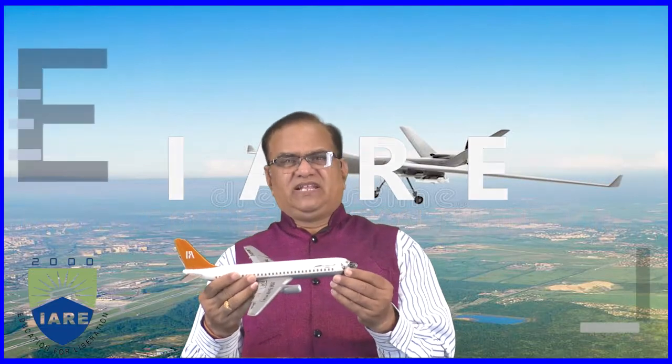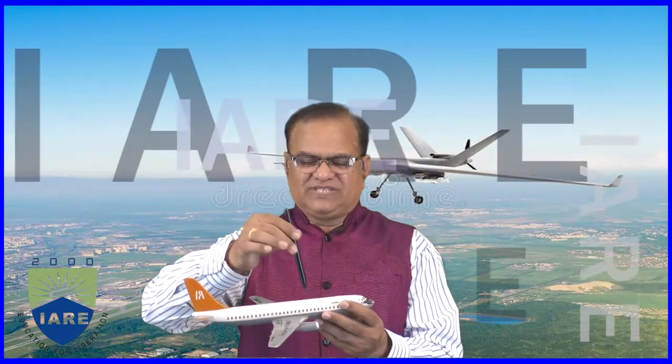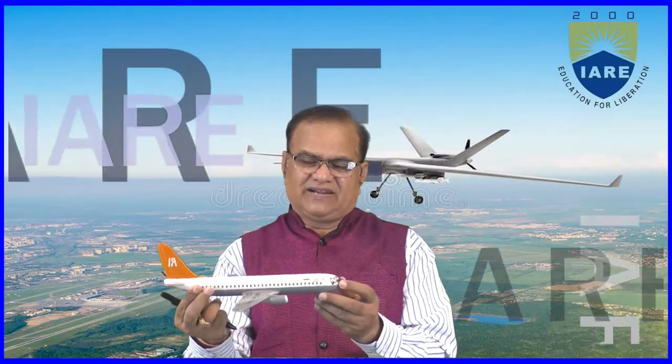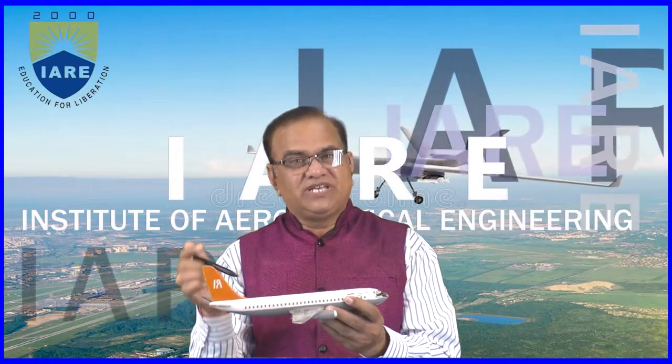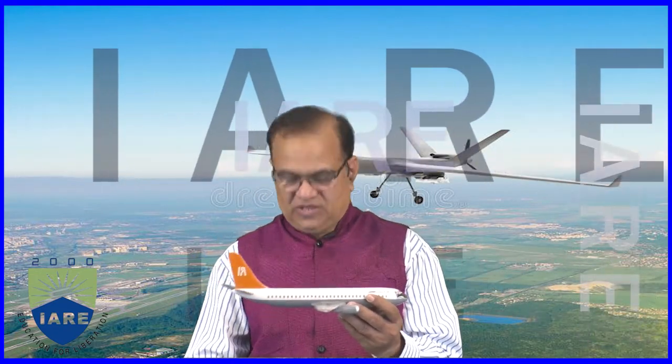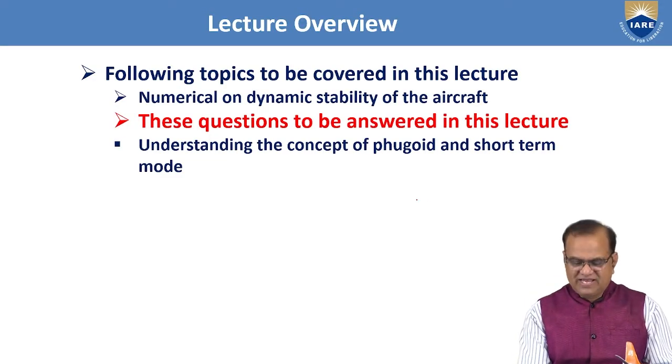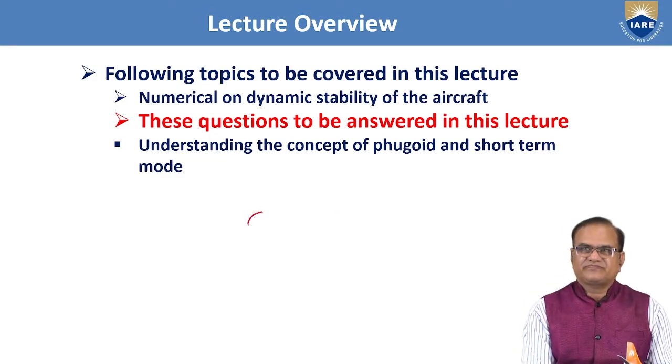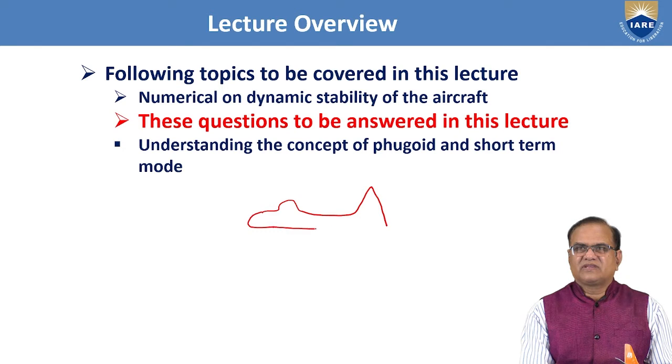So you can see this here. This is the aircraft, and here are the CG and the AC. If the AC is behind the CG, this will try to make the aircraft nose down. So here Cm alpha is negative, but Cm0 is also negative. So both cases are not good. Let me draw the initial case first. This is the aircraft, this is the wing, here is the CG, and here is the AC.